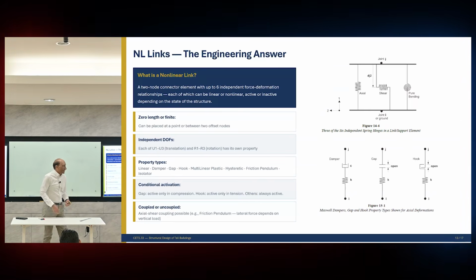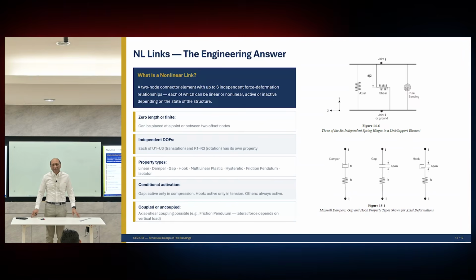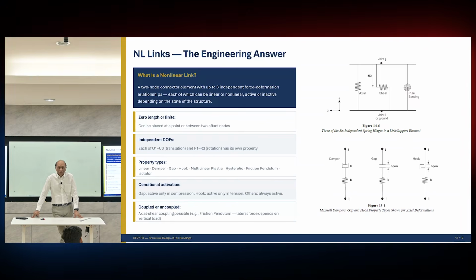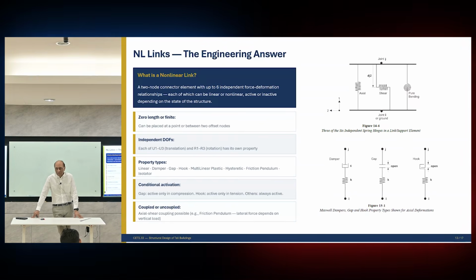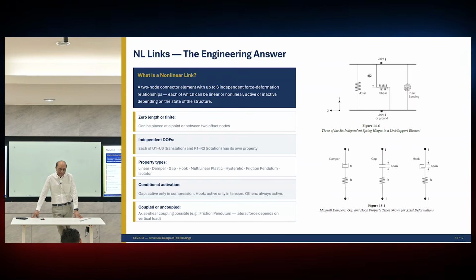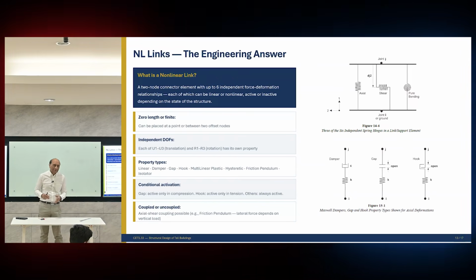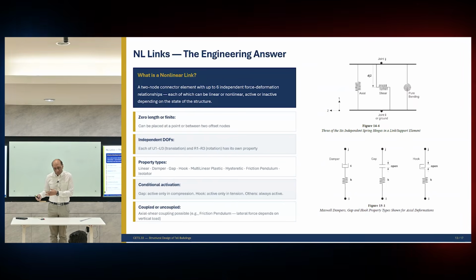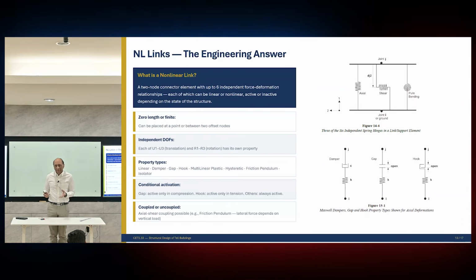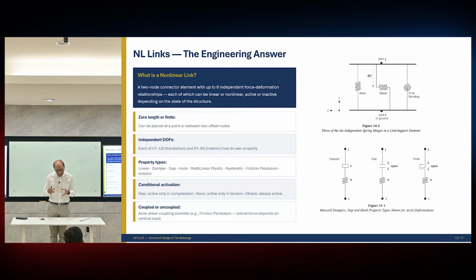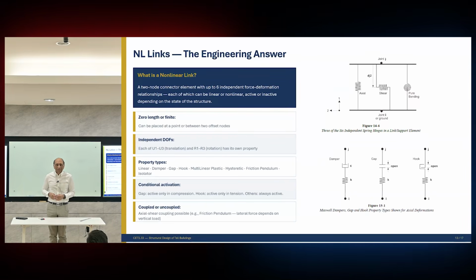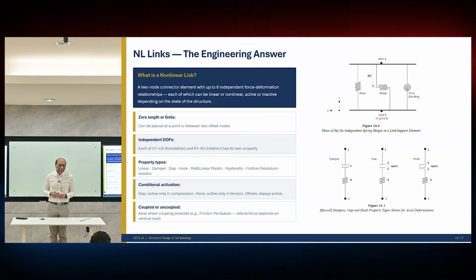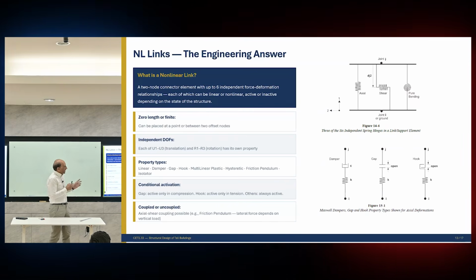But the problem is these elements are way too complicated. If you really get into that, I will not have time to discuss in detail, because this is not SAP, this is ETABS. But what I want you to understand is that whenever you face a problem that you cannot solve by any of these standard methods, and you want to go into further detail, then you should start thinking about using these nonlinear links, or links, linear and nonlinear.